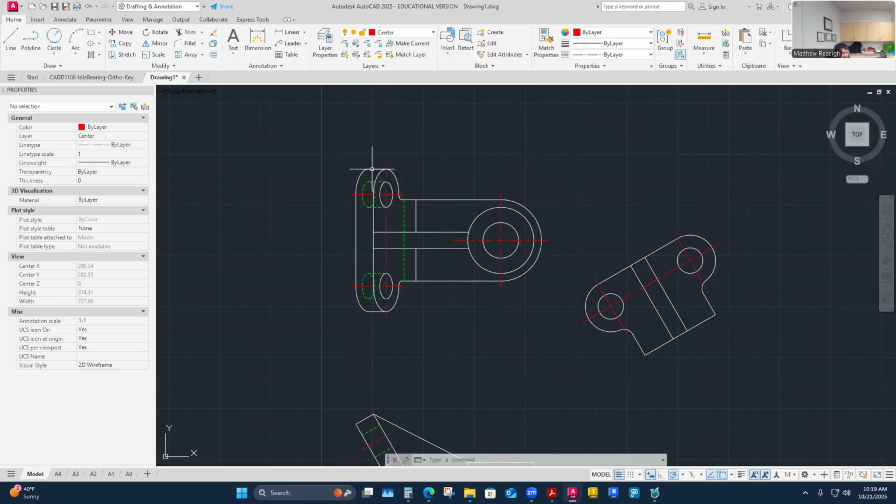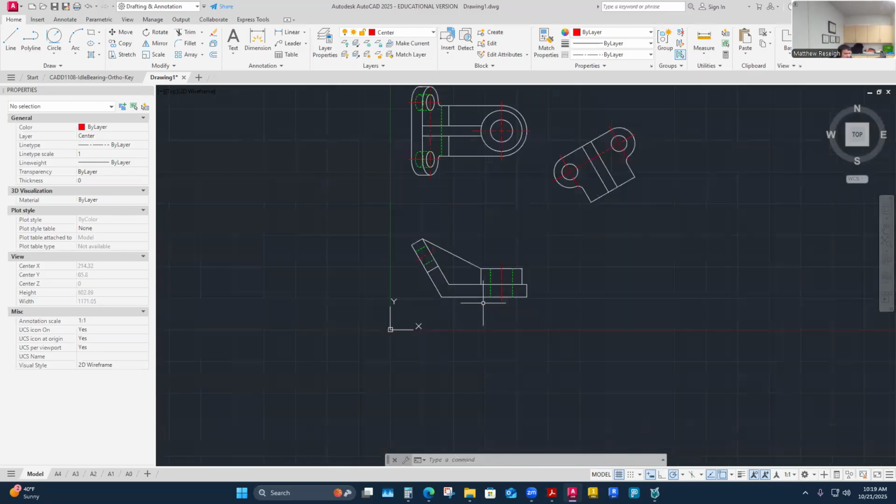And I could do the same here. I don't think I'd want a dimension from here, from the back or the front. The best surfaces to do that would be these surfaces where they're flat, and this outer surface to here is probably not a great dimension to pull. But what about if I extend this out through here, and I think of control now being the X and Y of the concentric nature of these, and basing other part locations from that, with the bottom surface maybe being a control.